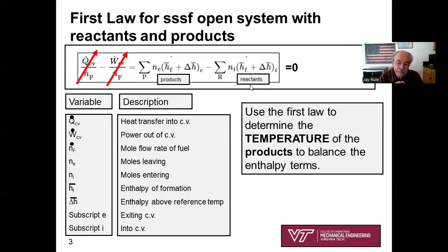The adiabatic flame temperature will be the temperature at which the enthalpies balance one another between what's going in and what's going out. Do you see then that the adiabatic flame temperature represents really the maximum possible T_H that can be achieved by your proposed combustion process?